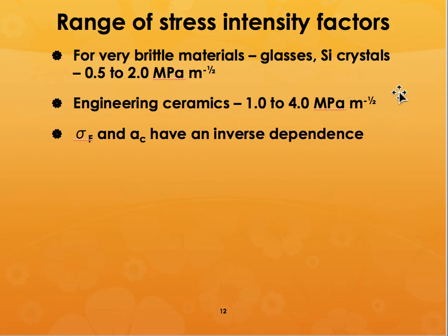It has been determined that for extremely brittle materials and glass, especially glasses, silicon crystals, etc., you have pretty low critical stress intensity factor of about half to 2 megapascals per root meter. Please note, megapascals per root meter is the unit for the stress intensity factor. And for engineering ceramics, you have numbers ranging from 1 to 4.